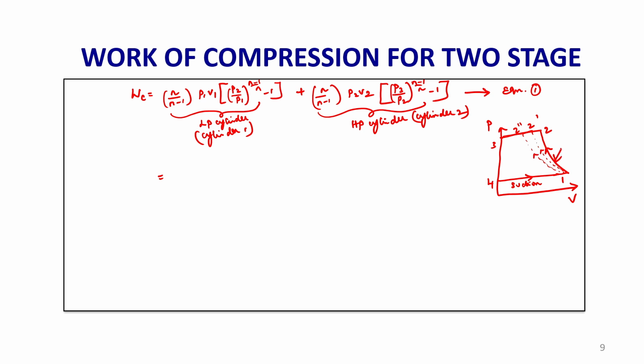This is the isentropic process or reversible adiabatic process, PV^gamma equal to constant. The second, this one, is the isothermal process, PV equal to constant, a constant temperature process. And this one is the polytropic process, PV^n equal to constant.